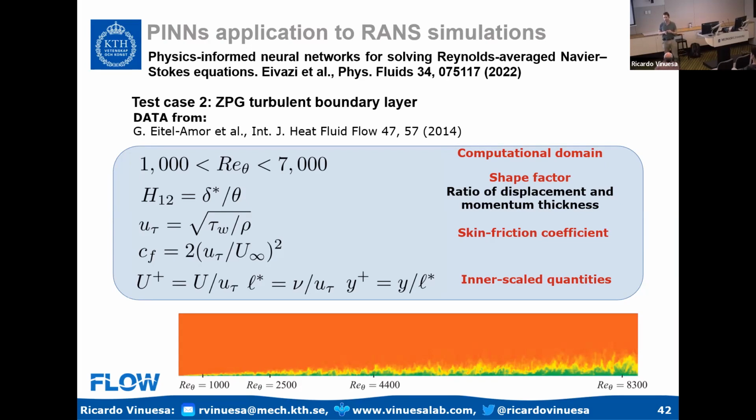That's the biggest challenge of going to turbulence: the same neural network is not going to be able to tackle all the temporal frequencies of all the modes. By the way, that's something that is solved with a transformer, as a side note. The paper that we published last year was with LSTM, but with the transformer, you solve the problem of the multi-scale character of turbulence. So that's also something to add to the mix.